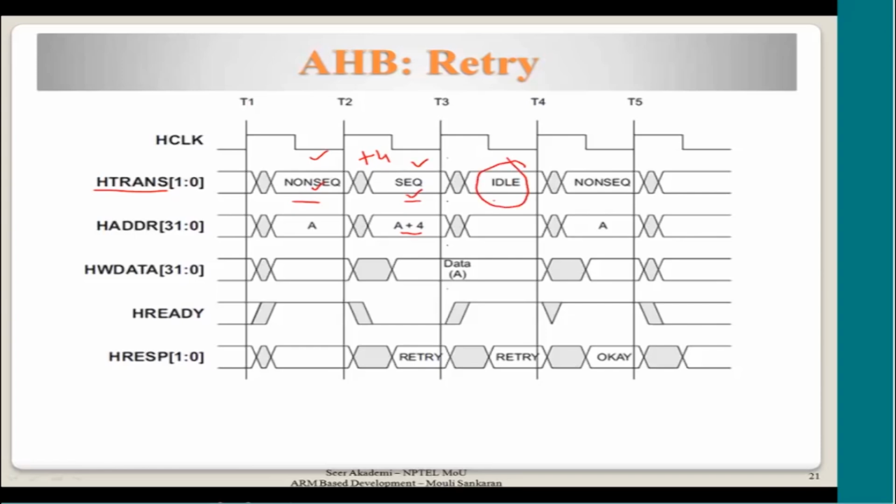The idle signal is generated when the slave responds with a retry, or it says that HREADY is low. That means after this transaction was completed, HREADY is low. That means the peripheral or the slave device has said that I am not ready to accept the next transaction. So because of that,